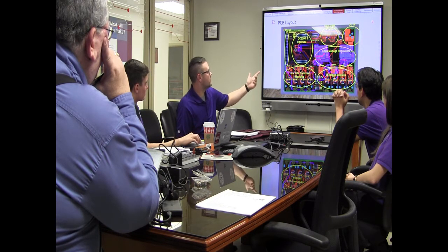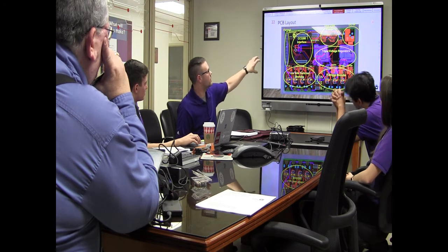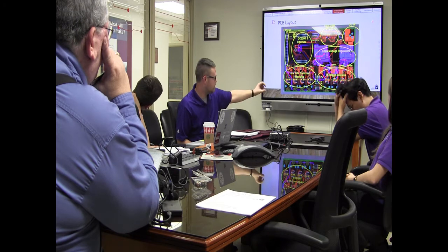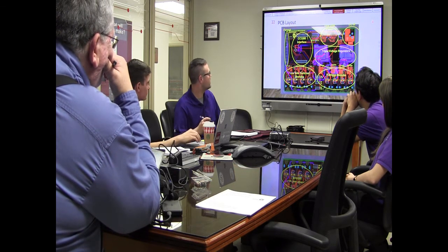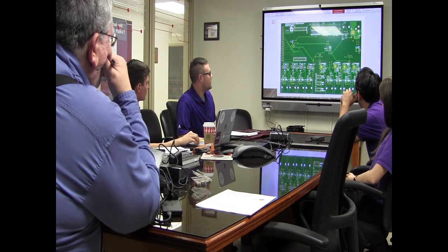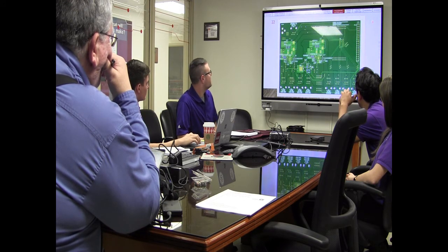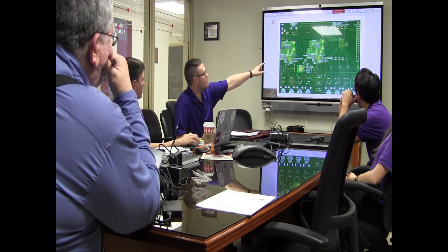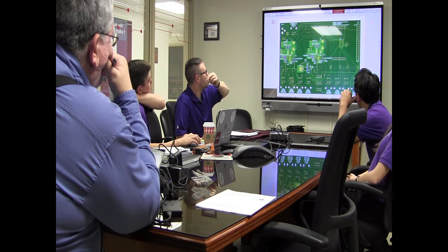And then triple voltage regulators. So the big ones are 5 volt regulators, and then the little one that's kind of hidden behind the H bridges is our 3.3. Go to the next slide. Here's a colored view of the same thing, and just seeing some of the footprint sizes. PCA9685 are 16-channel PWM generators up on the right-hand side. And just some of the routing and things like that.